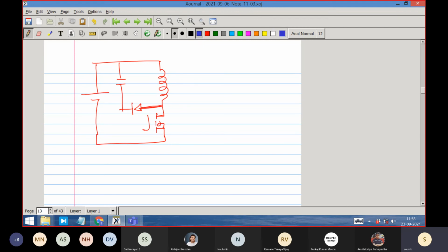I have not drawn the leakage energy separately. This part has two parts. One is magnetizing and another is leakage. The magnetizing part goes and gets coupled to the secondary side. But the leakage part, let us say, is the green color part. It is combined together as a coil, so you cannot see it, but it is there. So this part of the energy will go there, but the leakage part of the energy will go through the diode and capacitor. So the capacitor will charge in this manner.